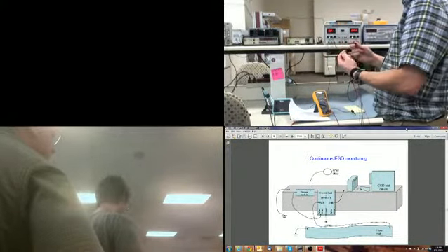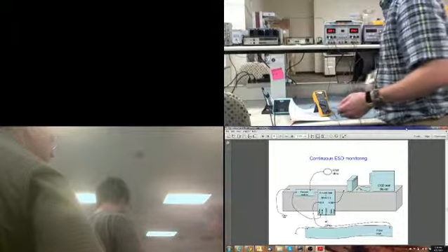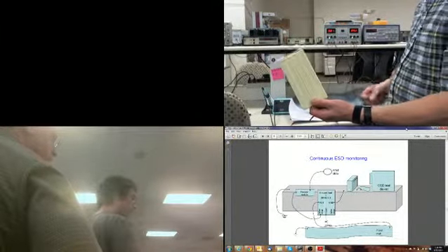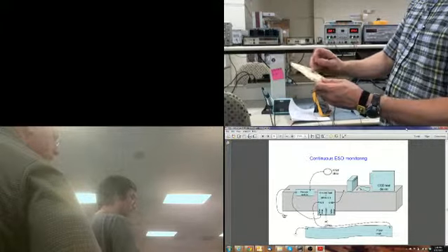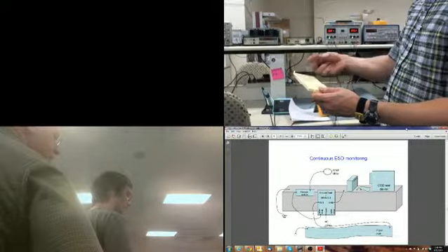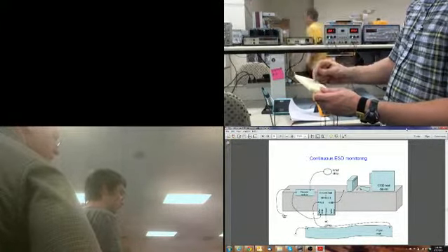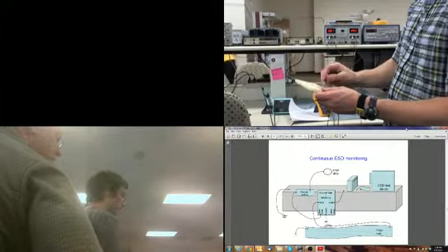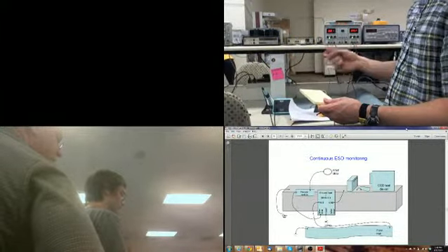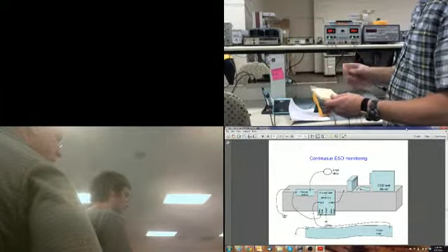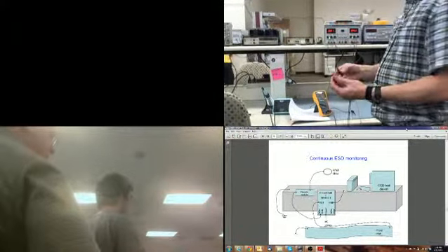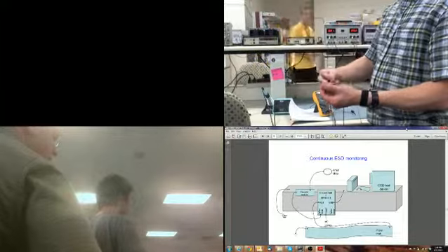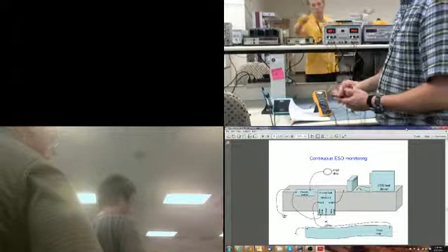When you connect those together, that's going to tell you whether you have a connection or not. This is useful when you're prototyping a board. Then you have your components in here, and you say, "Well, nothing's working." One thing you can do is de-electrify your board. You can check to make sure that this component lead is connected to this component because you know that it should be. So you can verify that those two ends are connected together by using the continuity feature on the device.